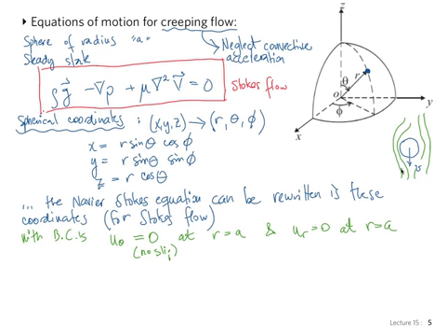It's a solid particle. So the r component would be normal to the sphere, right? Normal to the little sand particle. So obviously it has to be 0 because the fluid cannot go through the wall. Then we also apply a condition at infinity, that the velocity be unperturbed at infinity. And those are all our boundary conditions.